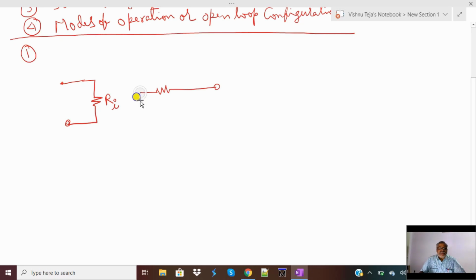The equivalent circuit of the operational amplifier can be represented with its Thevenin's equivalent model. Thevenin's equivalent model of the operational amplifier is represented with a single voltage source in series with a single resistance. Here the resistance is represented with R0 and the voltage source is represented with the gain AOL times the differential input VID, where VID is the voltage between the input terminals.